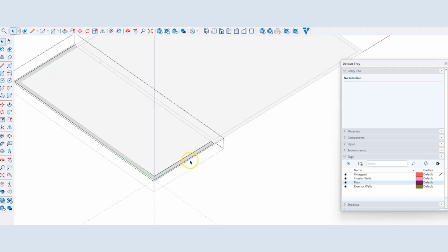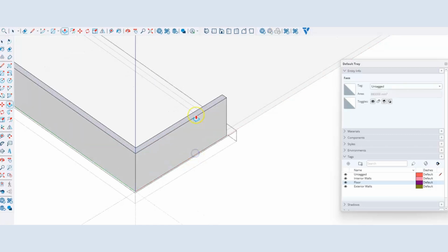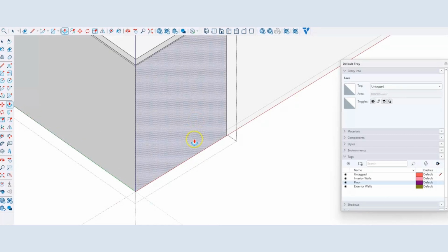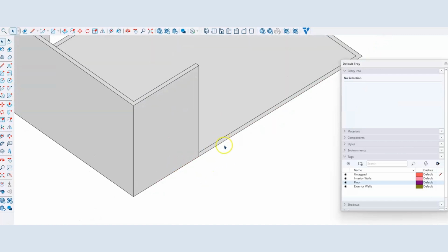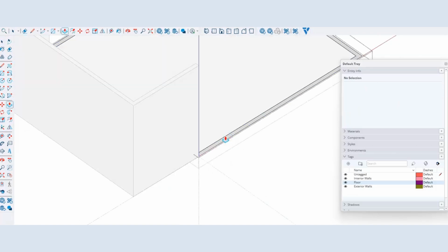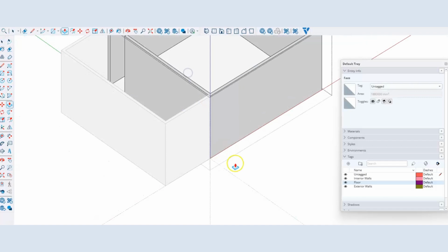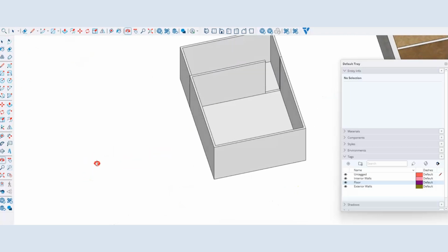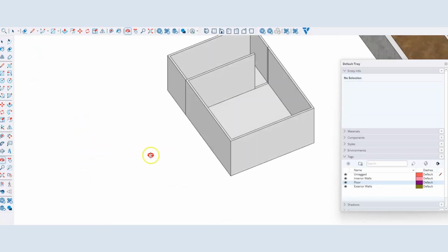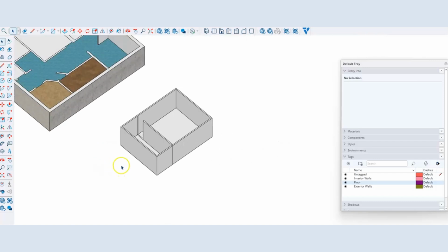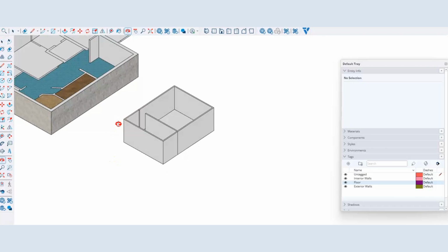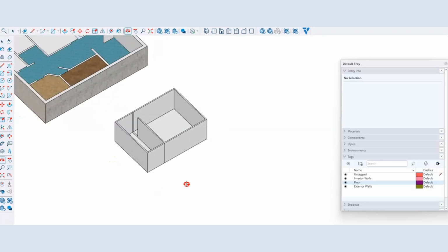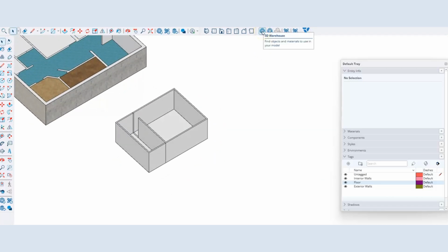All right, now I'm going to get inside my groups and pull up the walls. Double click in this one, push pull, P, 2700, and double click in this one, P, use the existing wall to go to that height. Okay, so it's starting to come together. And then we can experiment with textures again if we wanted to. You could even start to dive into the 3D warehouse.